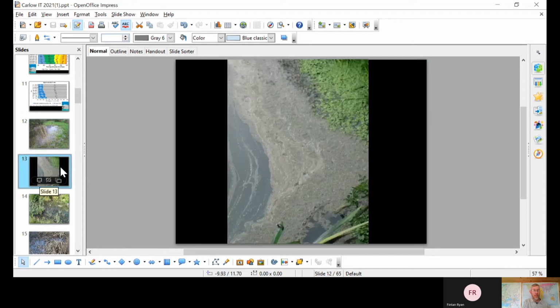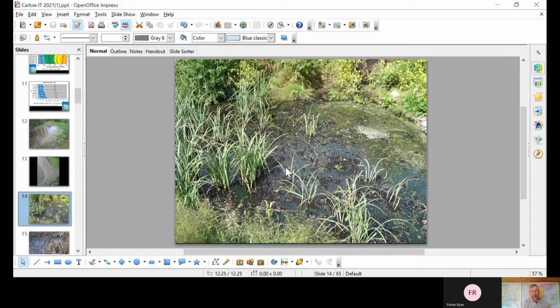And similarly, you can see there, this is a constructed wetland in Wexford. There's wetland plants at the edge of a pond, and the floating scum in the pond has accumulated at this sewage treatment wetland. It's accumulated where it's been stuck by the plants. So the plants act as a physical barrier to filter the scum that forms. Similarly, in a factory in the Midlands, this is a newly planted wetland, and you can see the green colour here where the algae is growing as a result of the sunlight and the warmth. Once the algae grows, it begins to get filtered out by the plants themselves. And those plants will thicken up more, filtering out this surface scum that's floating.